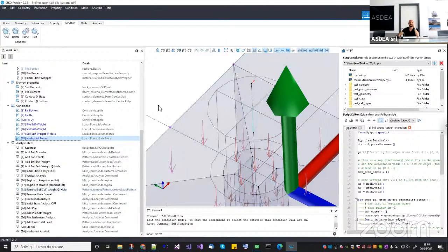So the first one, we have something in the chat. I see. So I guess that's why every time I try to change around the model for a more physically correct scenario, the simulation failed. Yes, that's the reason. Since OpenSees does not check if a node exists or not when it applies the load, it may happen that when you have a few nodes, there is a memory corruption, but it's so small that the application doesn't crash. When you increase the number of nodes, then this memory corruption takes more space and it can lead to crashes. But it can actually also lead to wrong results.